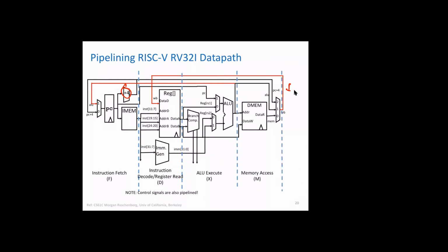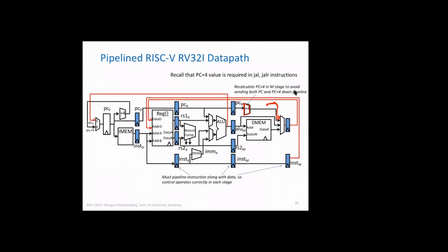So what they have done is that instead of that, they have added one adder. Anyway, we have to take the PC out, right? The same value of PC goes out. So for example, PC here comes here, the same value comes here in the next cycle, and so on, right? Which is being used. So what can be done is that we put an adder here, and note that this PC value is being used at different places.